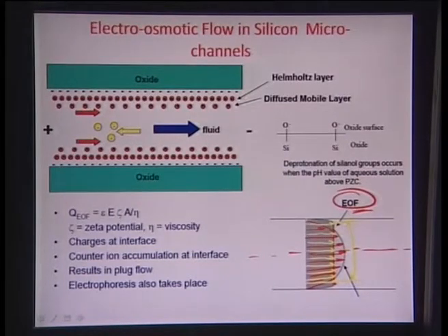Another interesting point here is the behavior of the flow around the surface in question till the double layer starts. So, this is essentially the Helmholtz plane. Okay. We have been talking about this a lot off and on, the Helmholtz plane. This particular layer here, as you see, has a kind of parabolic profile, which means that this is the layer which shears to give way to this plug like flow. Okay. So, the velocity really close to this surface here is 0, and the velocity here is some maximum value v, and the flow profile between the two is parabolic on both sides. So, that is how you interpret both these electroosmotic flows and the parabolic flows.